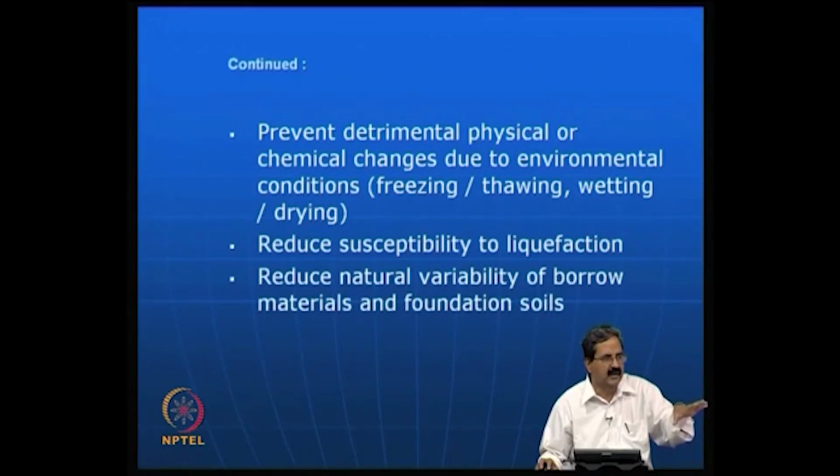So, there should be compatibility, in the sense of the degree of compaction, which is what you call it when comparing different types of soils. Degree of compaction is another term that we will be using, and the borrow pit materials should be compacted to their maximum possible densities, and you should see that the variability is small.